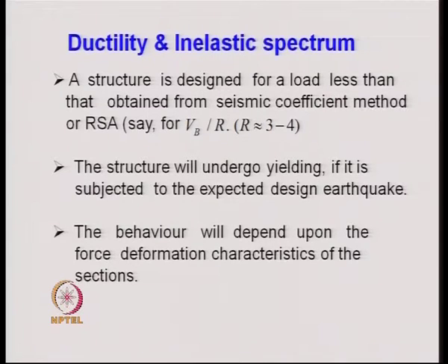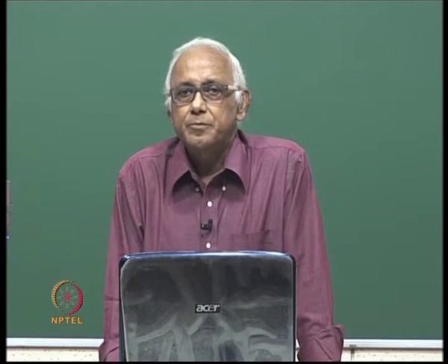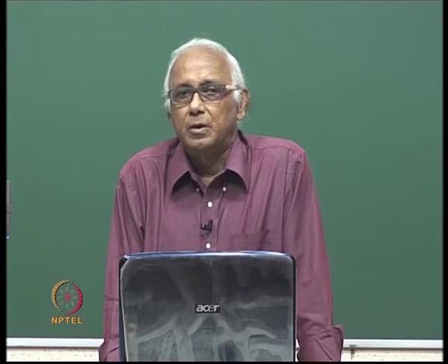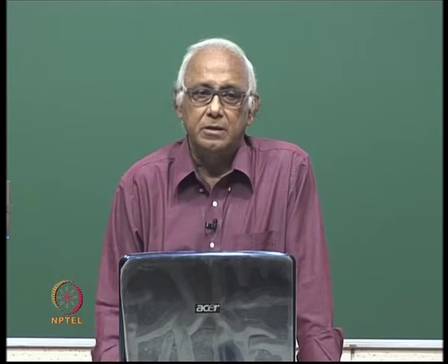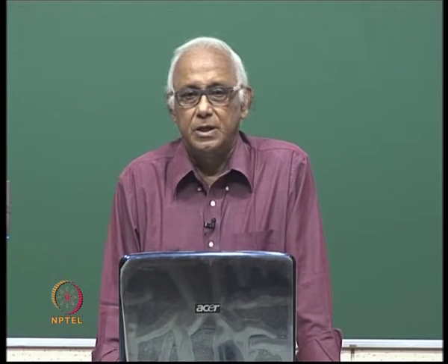With the help of pushover analysis, we try to understand the inelastic behavior of the structure after yielding during the earthquake, and also try to see the performance levels of the structure at different stages of the earthquake loading.